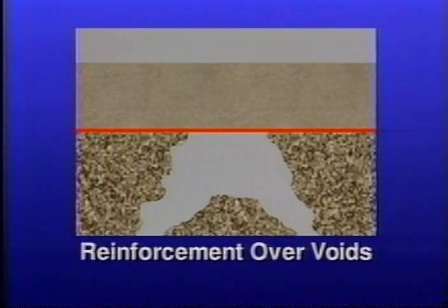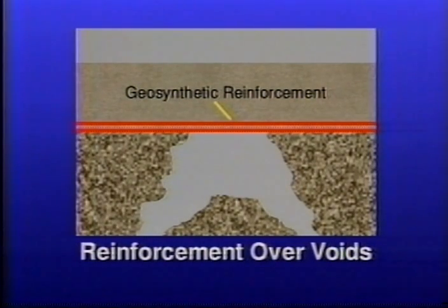Reinforcements may also be required to bridge over local weak areas or voids, as in karst or thermokarst topography. In this case, tensile reinforcement may be needed in more than one direction.